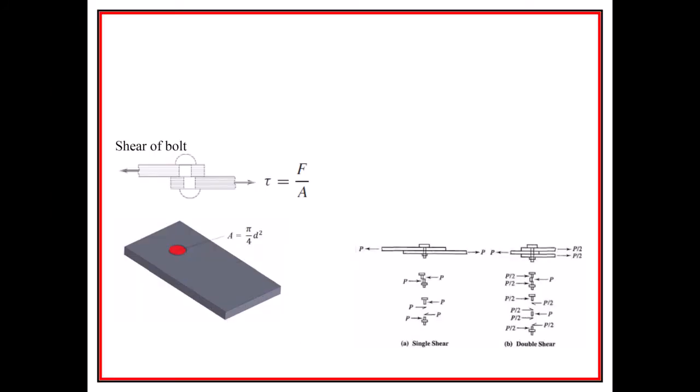That's going to be our shearing, right? So these are the bolts in shear, and once again, we got to be careful not to plug and chug as part of these. It's going to be F over A, but the A is going to be dependent on the number of bolts as well, right? So it's the cross-sectional area that we want to find.